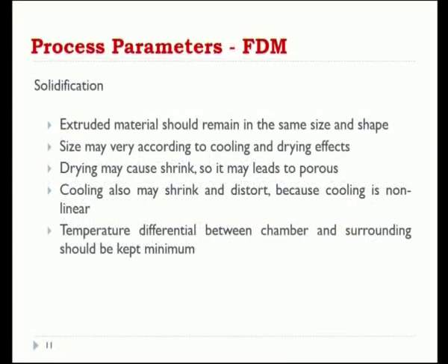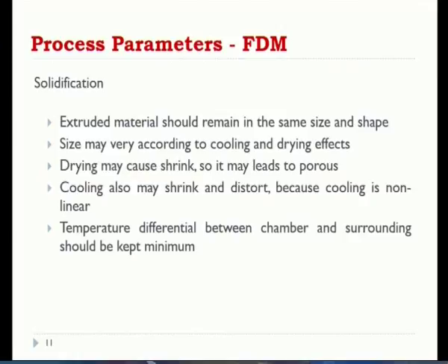And solidification, you can easily understand, because this is a normal process, but here the one major change is that once the material is extruded, it should remain in a constant shape and size. That is how the extrusion should work. But there may be possibilities of effects due to cooling and drying. What may happen if there is excess cooling or excess drying? There may be slight modifications in the shape, or there may be shrinkage. So those possibilities are there once the cooling and drying is not done optimally.